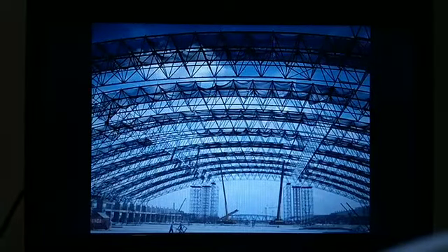And here you can see arch roof trusses. See how your arch roof truss is accommodating the span. How long would this be? It will be almost around 50 meters of length. Definitely it will be more than 50 meters. Why? Because arch action can accommodate such huge spans. And again arches also will be under a bracing system only, where they can accommodate more spans.